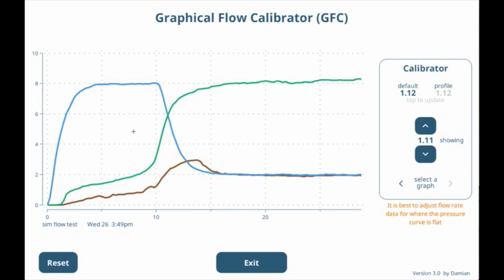The other stages would be infusion stages, and generally they're pressure control stages, so the flow calibration for the flow doesn't really matter. Flow's only turned off and on to maintain the pressure or let the pressure decline, or whatever the situation may be. So therefore, this is the most important area to calibrate. So that's what we do.